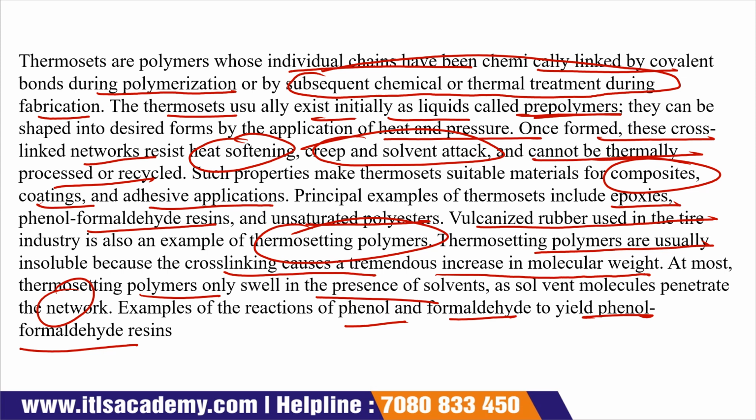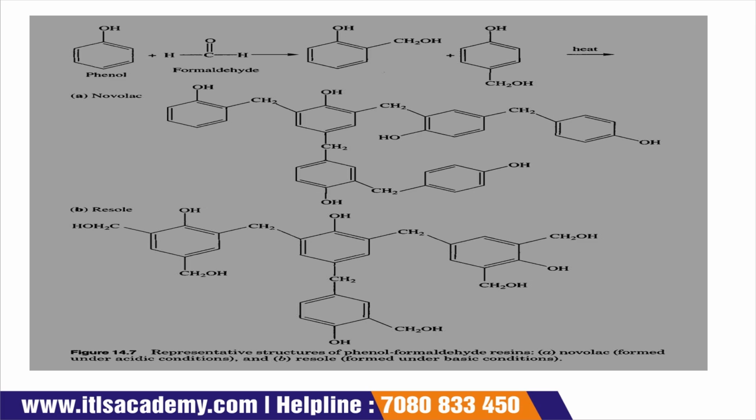Here the solvent penetrates inside the molecular network and swells it. Now the next is a diagram which represents the structure of phenol formaldehyde resins. Novolac forms under acidic condition and resole forms under basic condition.